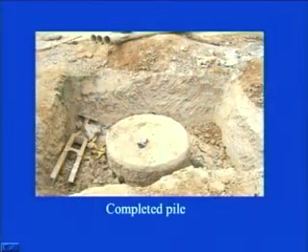But to ease construction and workmanship, all these measures are taken care of while construction is going on. You can have a look here, this is a completed pile. It was of 1 meter diameter when we were there at the site. So we recommended that a 1 meter diameter pile should be there. This is how it looks with reinforcement and all.